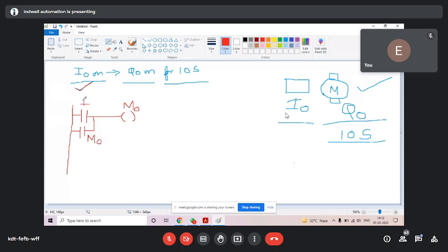So think nothing, just do this whenever you have a start signal. So I have a start signal, and what I have done is, I latched the start signal with a flag. It is done. Important thing here. Don't miss this while making the program. If you miss this, your program will be wrong. It's my guarantee. So this small thing you always follow. The small thing is, answer me please. Everyone text me.